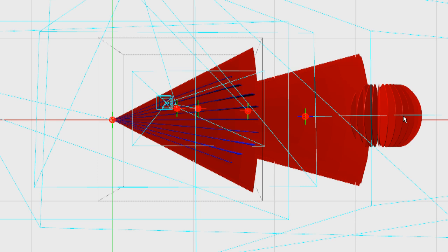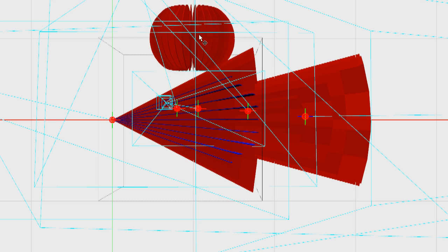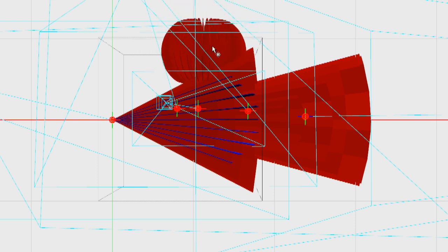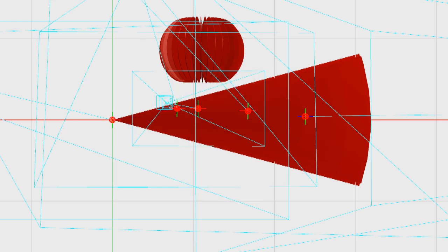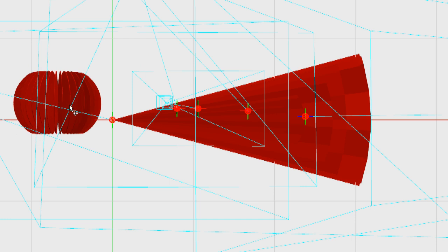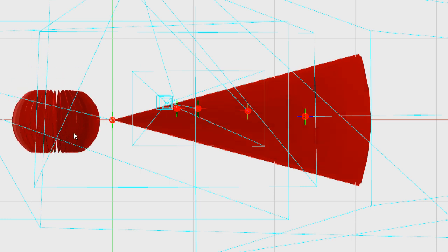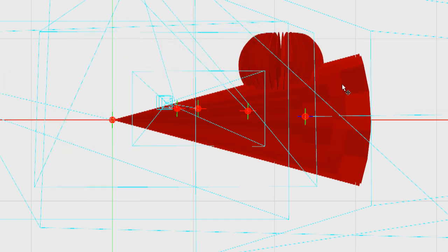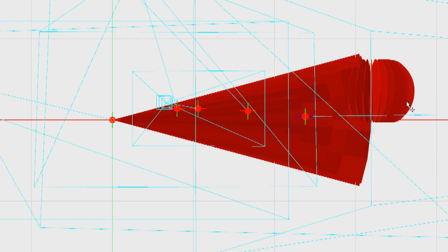So the downside, of course, is that the field of view is not quite as good. So with the diversity receiver, 11 decibel, I can be flying here and get a pretty good signal. But with the Yagi, I'm out of range here, look. And again, behind it, forget about it. It's not even going to know you're there. Yeah, above it. You have to be very, very specific about where you're pointing your Yagi.